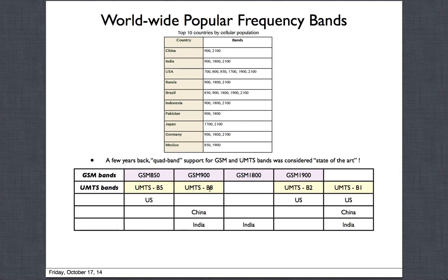If you're using GSM, you could be using GSM at 900 megahertz, for example, or the same phone could also support things like CDMA or WCDMA or any of these other standards. Then it will also use the same band, but it will be more like UMTS band 8. You will never use both of them at the same time.